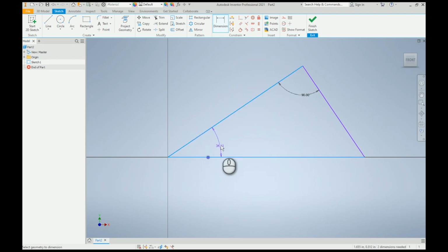This angle by design will be 180 degrees divided by the number of slots. In the design, it is half of the advance of the Geneva wheel when the driving wheel does a full turn. For example, we will design a wheel that will advance 60 degrees per turn of the crank, therefore we need 6 slots. Then 180 divided by 6 is 30, which is half of the advance.